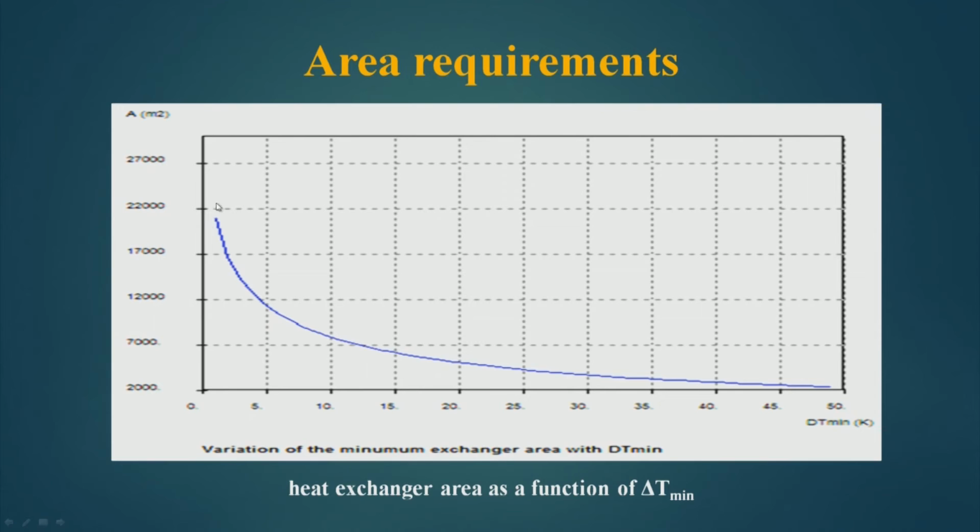So, this is the decrease in area of the heat exchanger network. As the area decreases, the fixed cost of the heat exchanger network will also decrease proportional to the area, because we have seen that the cost law is A1 plus B1 area to the power C1.